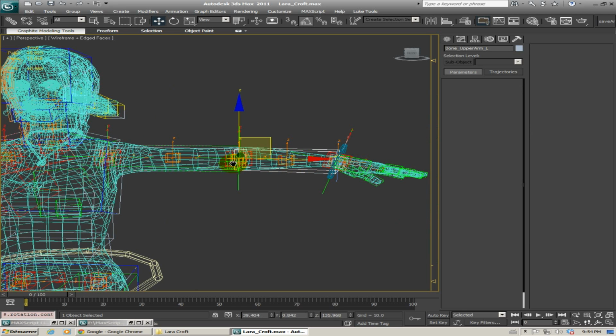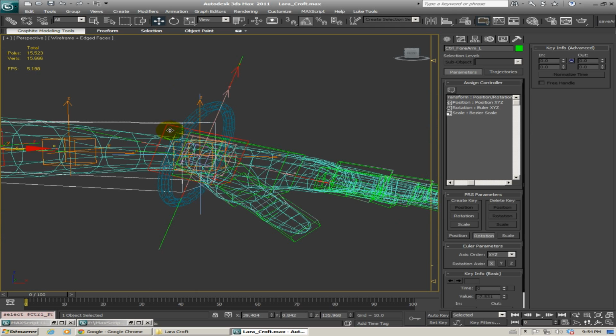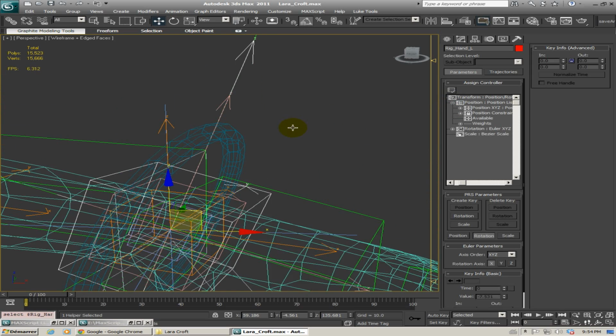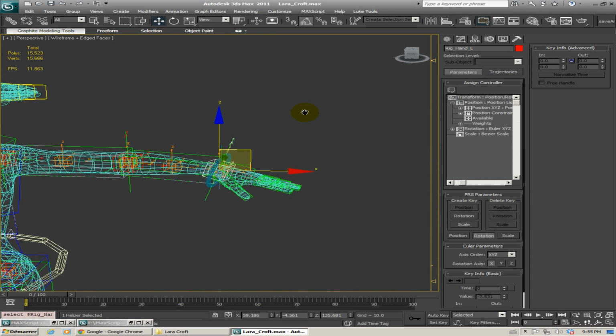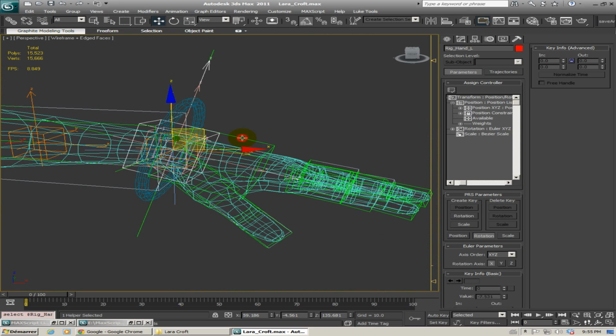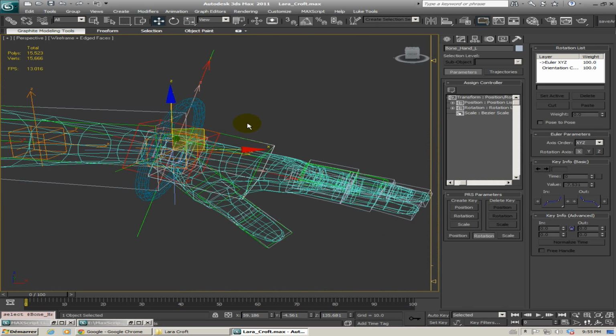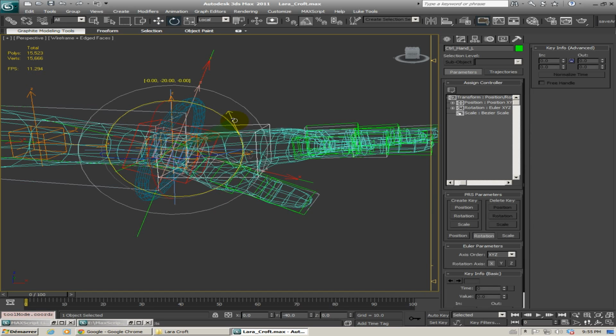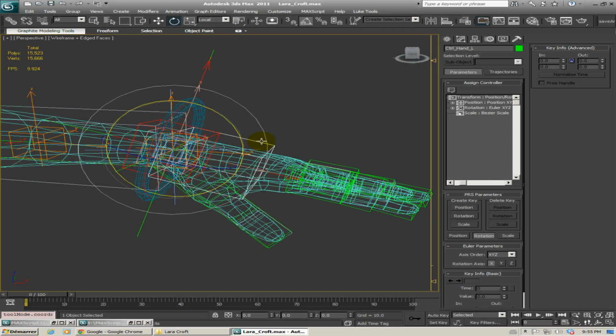Did I do this for the helper here? I'm going to verify this. This one was only in position. I don't need the orientation for this. It's really just position, because these controllers will follow the IK system when the IK mode is on, so I can use these controllers by themselves and it won't change for them.